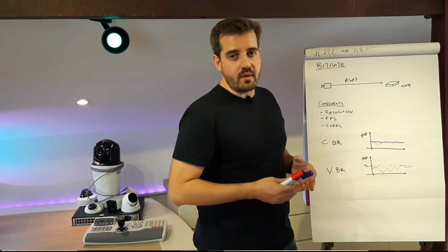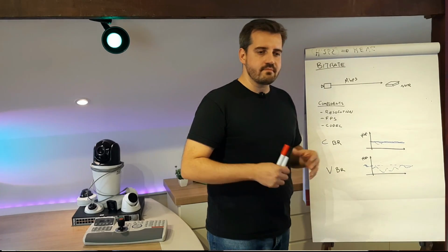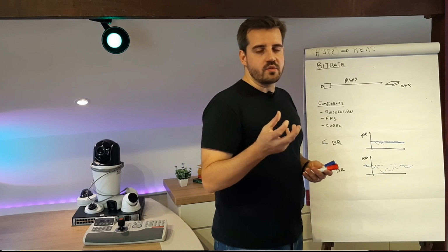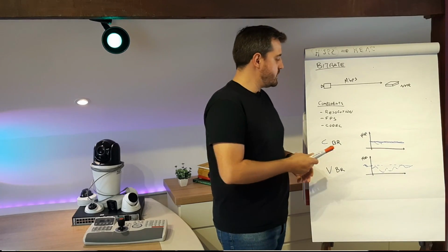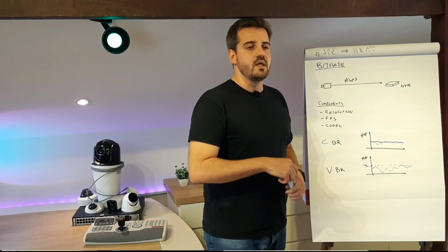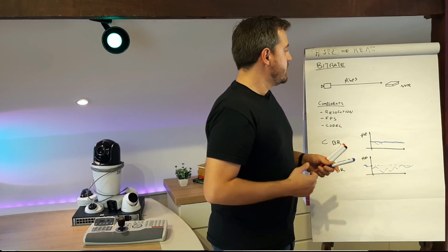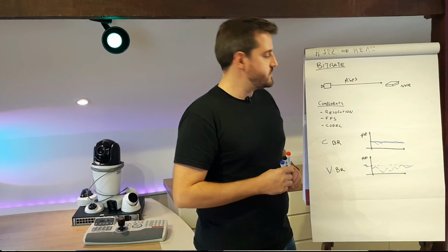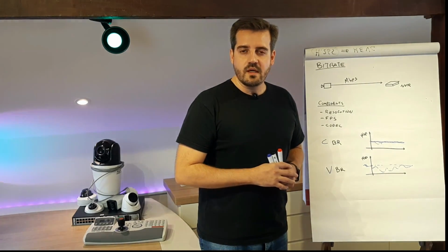If it's a very cheap camera and you set H.265, it will not necessarily have issues, but it decreases the camera's capability to do other tasks as well. So it's very important to check that your camera supports H.265, for example. Check whether using H.265 at, for example, 30 frames per second will not impact any other features the camera has. Okay, and I think that's it. I'll see you in the next class.